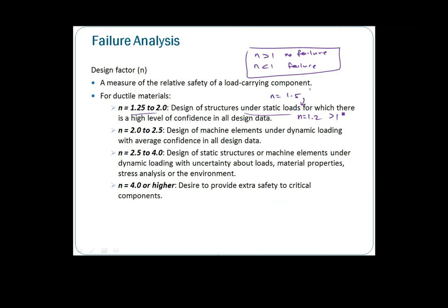You need a higher factor of safety for the so-called uncertainties that you do not know, so usually we go higher. But we don't go too high, because if it's too high, then it will become over design. You increase a lot of things: your costing, materials, everything will increase. So this is just a guideline.